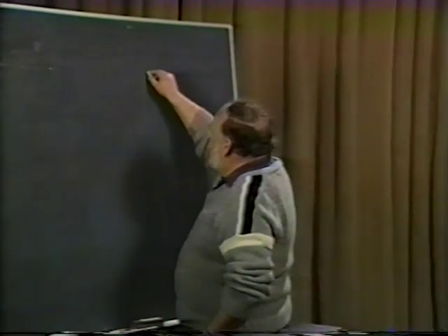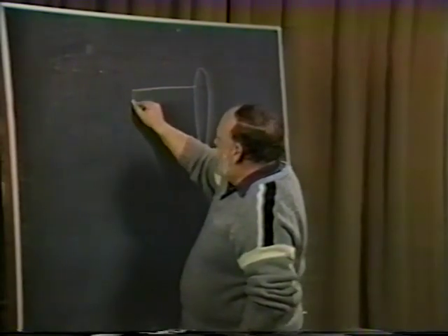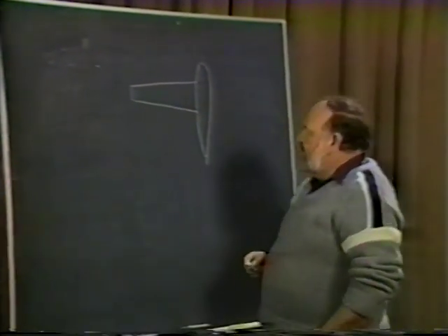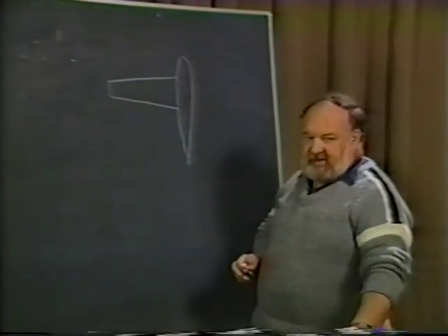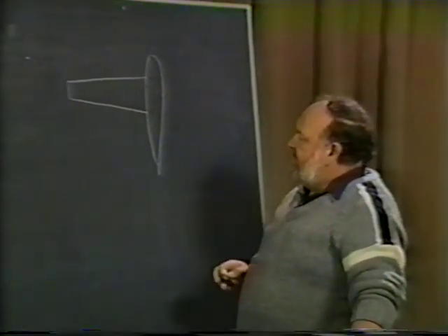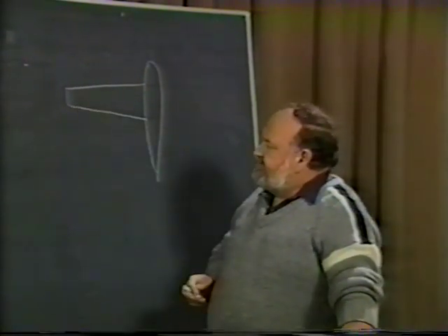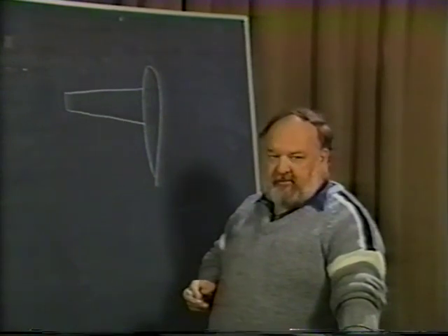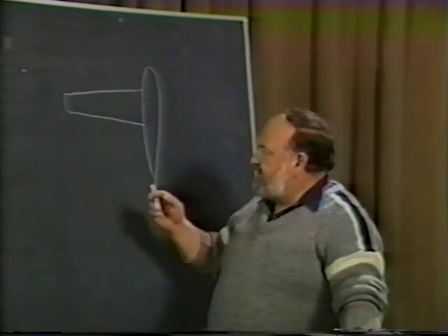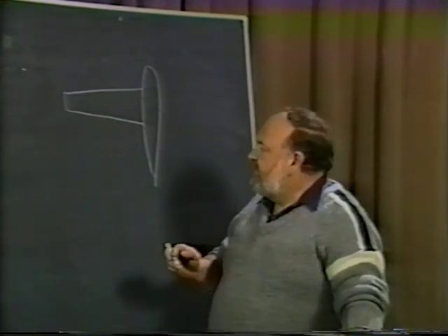Let's take a look at the basic wing plan form of a normal general aviation airplane. This would be a top view. We might look at a tapered wing section. This is somewhat of a standard type of design you see on an awful lot of airplanes. Fundamentally, this aircraft plan form here is quite good, except for maybe one possibility, and that is that the tapered section tends to give us a lower Reynolds number on that airfoil section, and the lower the Reynolds number, generally, the more adverse the stall pattern might be on that particular aircraft.